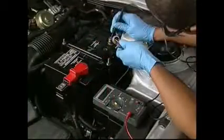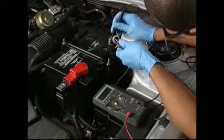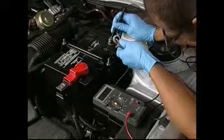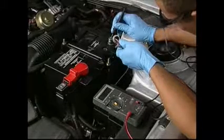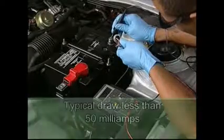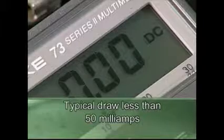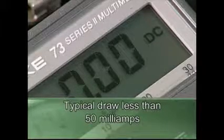You can use this time to disconnect the underhood lamp, if the vehicle has one, by removing the bulb, disconnecting the connector, or by pulling the fuse for the circuit. Once the onboard computers have shut down, you're ready to do the test. Touch the black probe to the negative battery terminal, and then touch the red probe to the battery cable end. On most vehicles, the current draw shown on the meter display should be less than 0.050 amps, or 50 milliamps.